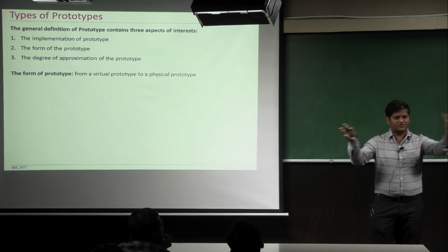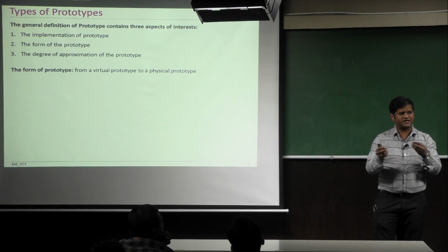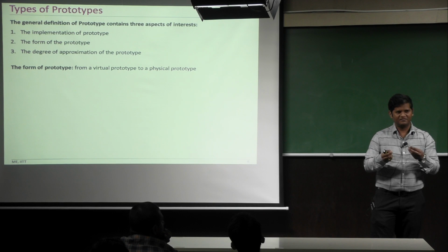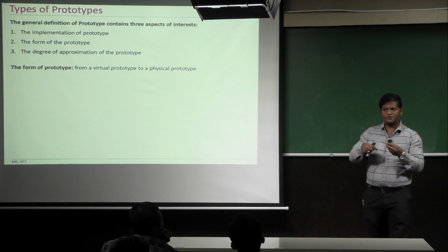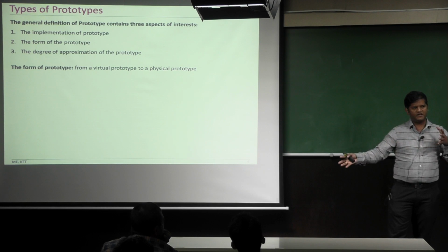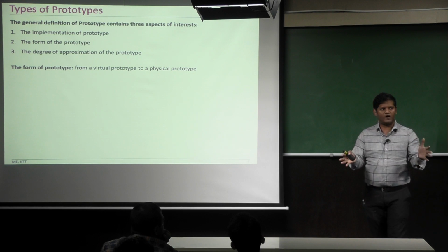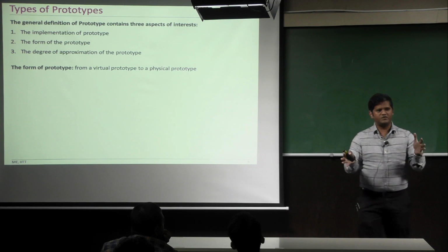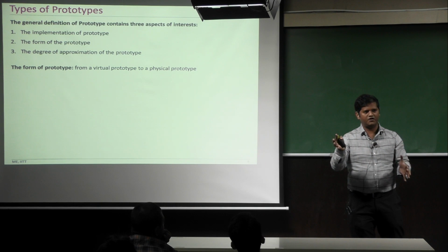All these tubular sections are assembled by welding. Once you perform the welding, at the end, if you see the final assembly, it's not as per the required shape. There will be some form of distortion in the component or in the final chassis.